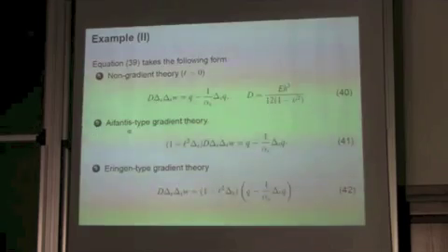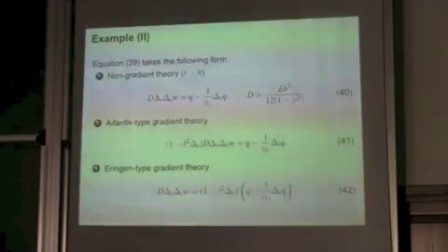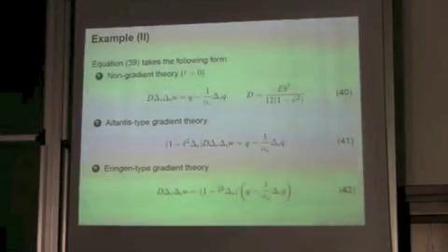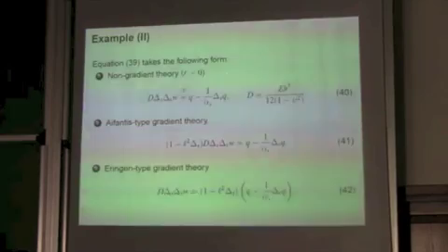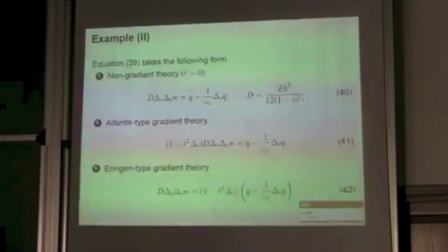If we have this Ru-Aifantis type gradient theory, in this case, the modification will be on the left-hand side of this equation, because we have an influence on the strains, and so there must be some changes on the left-hand side of this equation, which is presented here. For the Eringen type, we have the influence for the stress part, and so it is clear now there are the changes on the right-hand side, and so we have two types of equations.